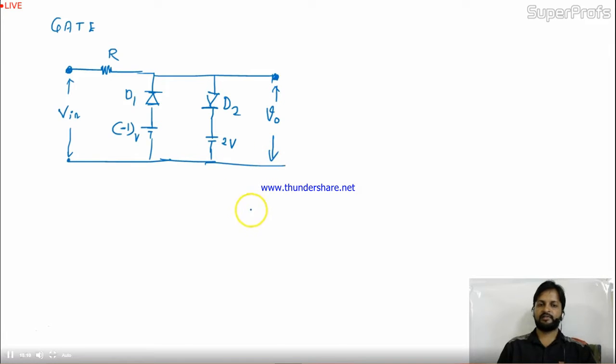Okay, and the question is now, the question is 2 silicon diodes. These 2 are the silicon diodes, and the question reads as, with a forward voltage drop of 0.7, yes, 0.7 drop is there if they will conduct. We have to assume this, it's given in the question, are used in the circuit shown in the figure. The range of input voltage Vi for which the output voltage V0 equal to Vi. So what they are saying, find out the range of V in, input range.